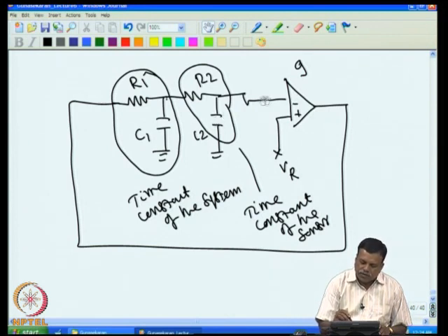And then what we are doing is the temperature sensor output is given to the comparator or an amplifier, and then we compare it with the reference. This is a set value. The difference between these two is amplified, and the amplifier voltage appears here.